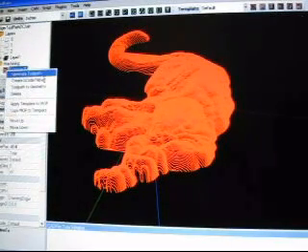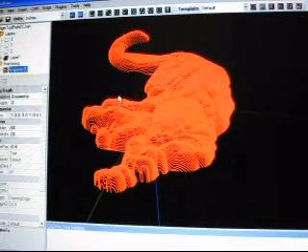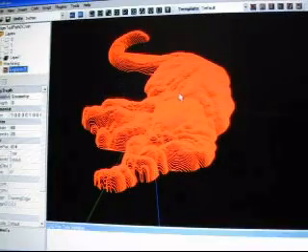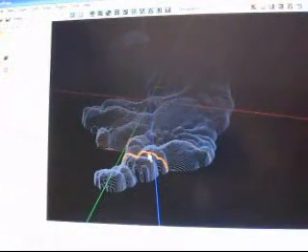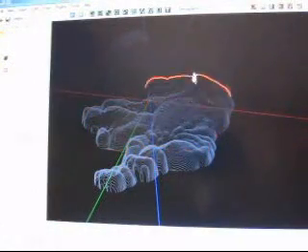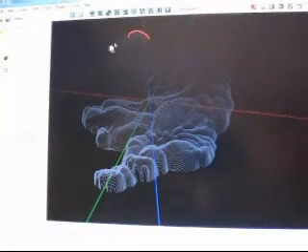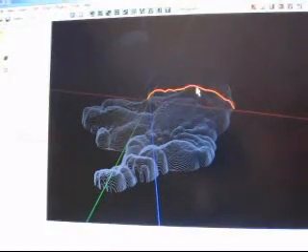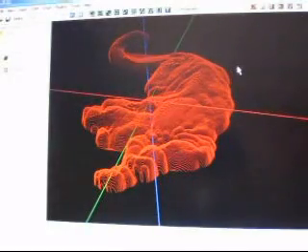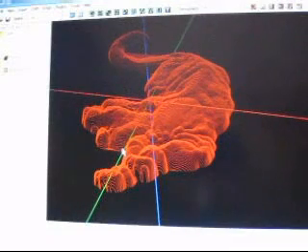But I'm going to generate the toolpath and see how fast that took. That was like instantaneous. Boom. It's done, because we converted all of these lines to polylines. This system likes polylines for some reason. So when you have done that work ahead of time, the toolpath creation is instantaneous. You could save that G-code file and it's like snapping your finger. It's actually that fast. So that's the benefit of doing that.